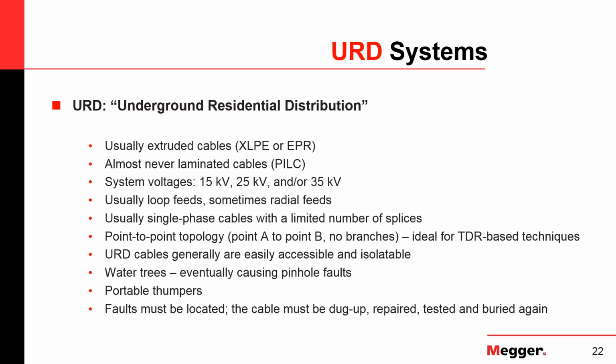And those electrical trees, they will grow forward at a very high rate and then make the cable fail. And the typical failure mode, since this happens very punctually, like very locally, is that the cable blows out and you have these pinhole faults.